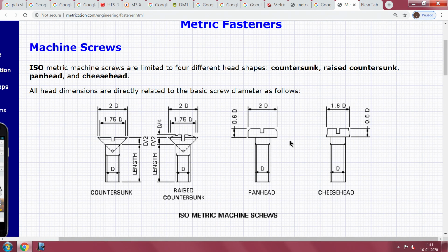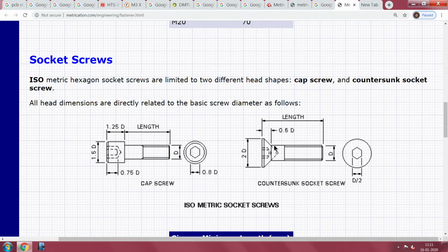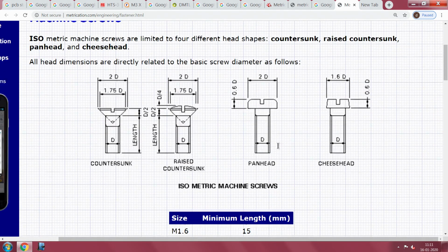Both these things are actually probably the best fasteners you can think about, because you can have a hole which exactly corresponds to the diameter, and here also the fabricators have standardized on the drill bits which they stock. So, for a 3 mm screw, by default a 3.2 mm drill bit is used. Why the 3.2 is used is it gives an accurate location.